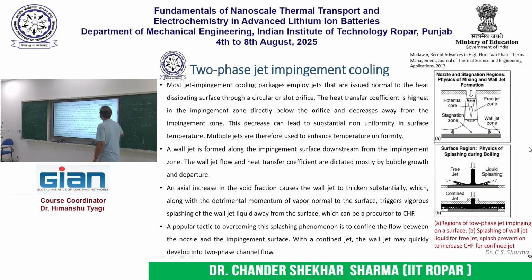Okay. And then further, if you want to increase heat transfer, you can mix both the strategies in the form of a jet. So two-phase jet impingement, where jet is impinging on the hot surface and it's also undergoing phase change. So there you get the benefit of both the flow field of the impinging jet as well as the latent heat absorption due to boiling. But again here, the challenge is how to control this phenomena so that the net overall flow always remains within our preferred type.